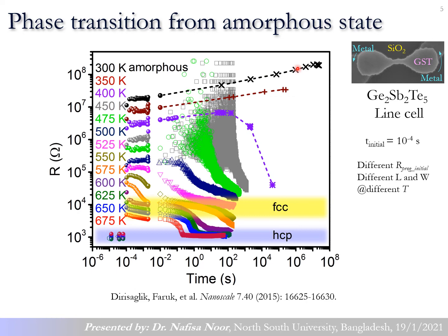And again, I would remind you from the previous slide, we said that this is a spontaneous process and a thermally activated process, but this going down nature of the resistance is known as the crystallization process. Now these can be modified when we go to higher ambient temperature. So at room temperature, we can go up to 10 years of retention time in the PCM.